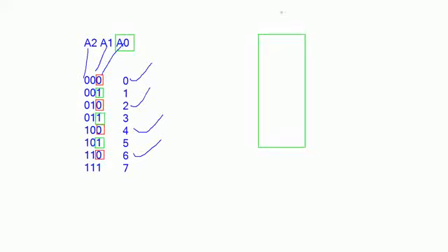So if I'm calling one of the memory devices as even memory, don't think that all the memory locations are even only. It is made as even. Actually it is having the sequential memory only, but it is made as even based on the A0. One of the memory devices is called an odd memory device, meaning it is made odd with the help of the A0. But if you take them individually, without considering the A0 combination, they are the sequential memory locations.